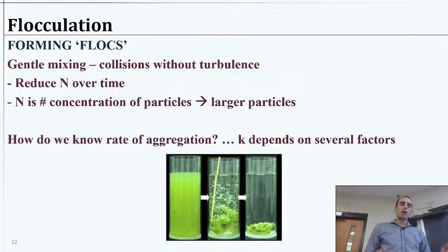So the right way to make this happen is to give them gentle mixing. Because if we have particles and we want them to stick together, if our water is too still, the only thing that can get them together is diffusion, and that's probably going to be too slow. They're almost never going to meet. We also don't want to shake it vigorously, because then if we did have a particle stuck to another one, we might break it apart with the shear forces, right? So we just want a gentle mixing, give them time to meet, but not so forceful that we're tearing them apart. So collisions, but no turbulence is best.